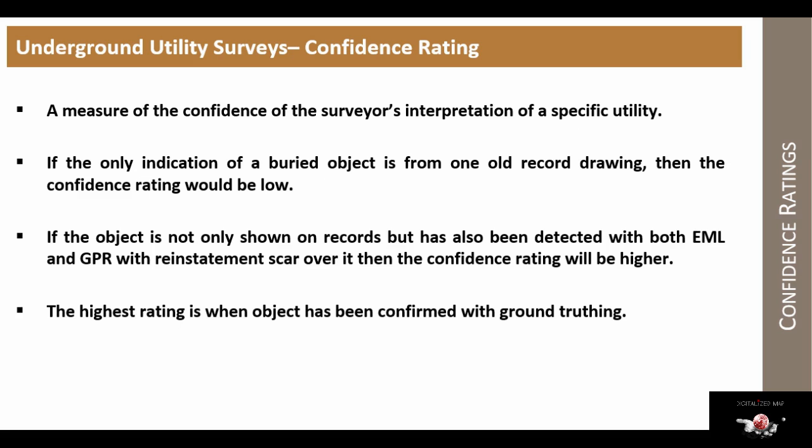Underground utility surveys, confidence rating. A measure of the confidence of the surveyor's interpretation of a specific utility. If the only indication of a buried object is from one old record drawing, then the confidence rating would be low. If the object is not only shown on records, but has also been detected with both EML and GPR with reinstatement scar over it, then the confidence rating will be higher. The highest rating is when object has been confirmed with ground truthing.